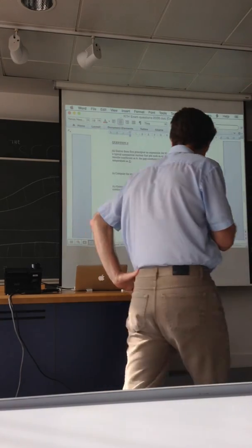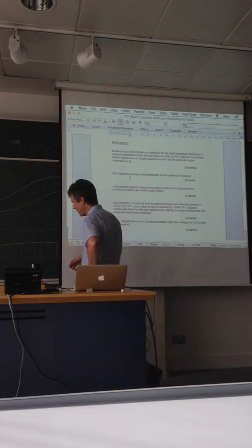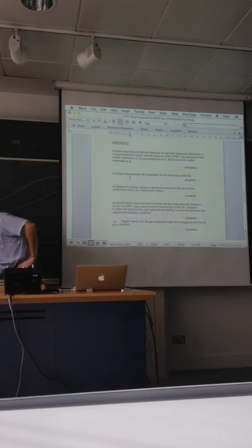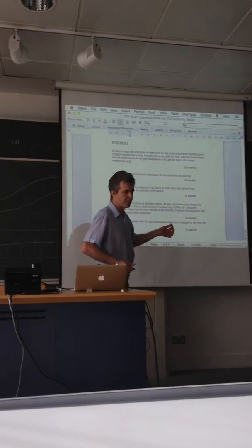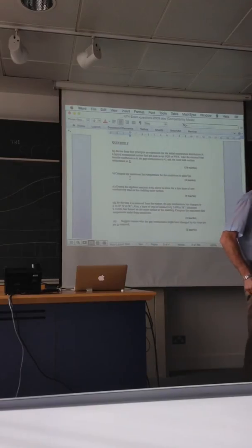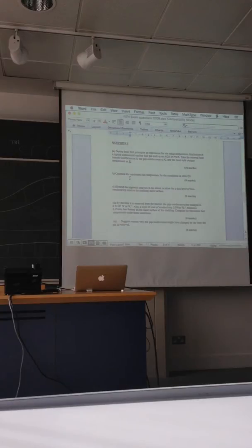Locally at a point, you'd say that the rate of generation at the point must equal the rate of flow away from the point, with or without any rho Cp dT/dt if there's actually any change in the stored energy at that point. It doesn't actually say steady, so we could use either then, I guess. That would be fine. So something like the divergence of Q would equal the local volumetric rate of heat generation.